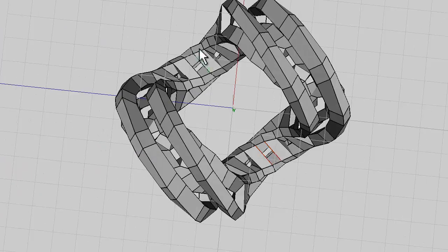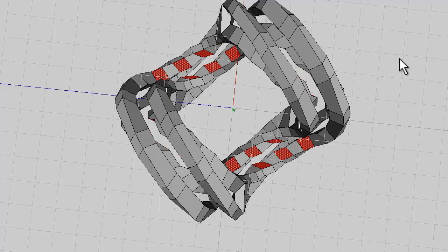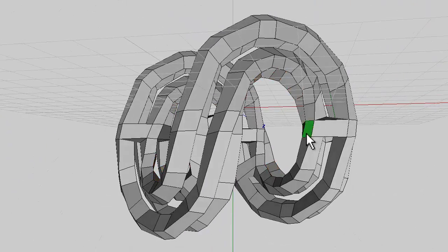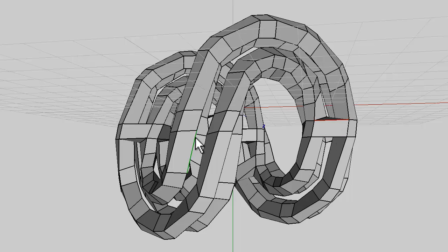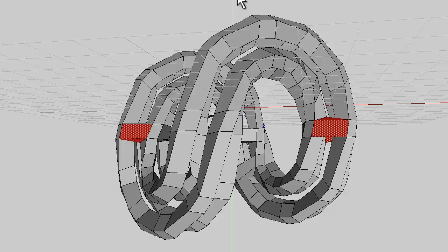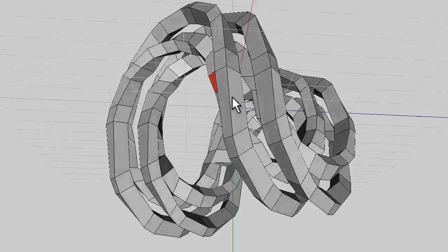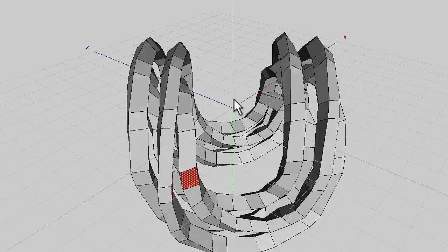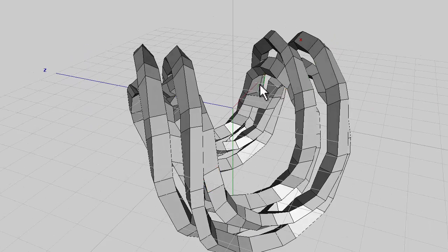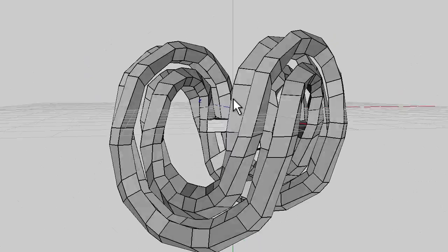Right, so edge, edge, edge. I did mention this was quite fiddly, didn't I, to begin with? So G, identical, I, key, G, then they're all the way around, then get all the faces and delete all the faces. So how's that looking? There's 1 or 2 oddments here, so get that one, identical, G, face, delete. Nearly there, actually. Right, on to the next fiddly step soon. You'll probably not be pleased to hear.